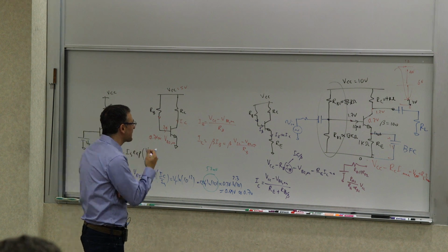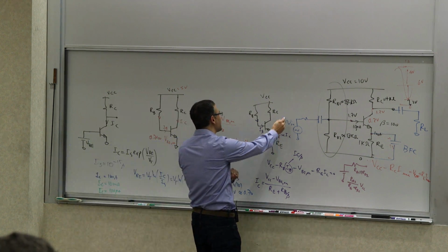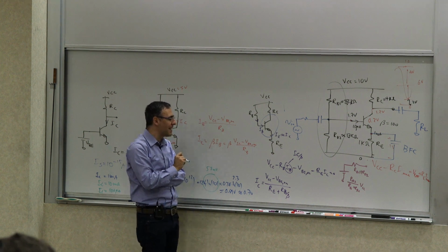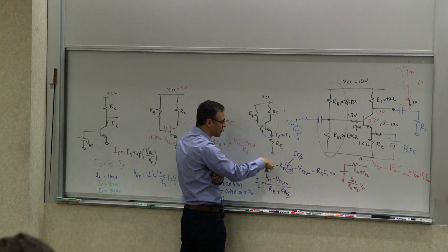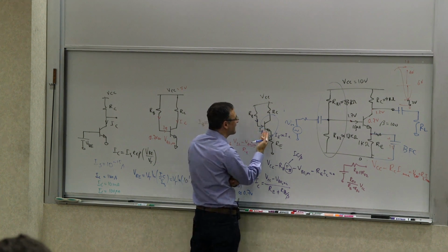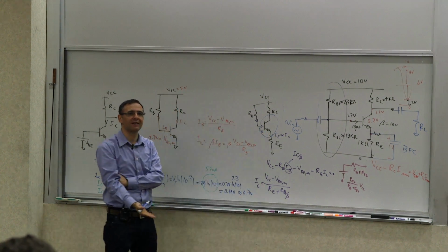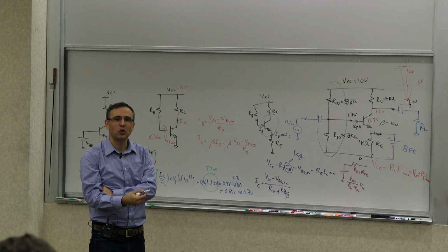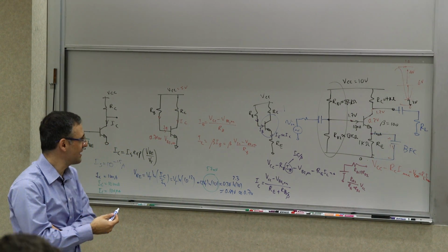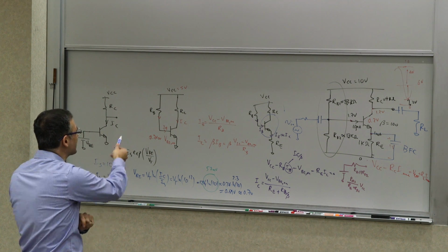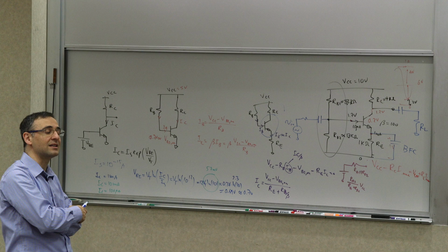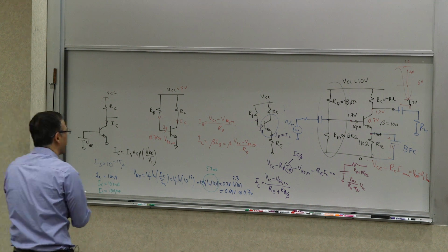Now, the interesting thing about this is that by biasing it this way, if you choose the values such that you have the proper relationship, you have effectively made it less dependent on the specifics of the transistor. You don't see the exponential there anymore, right? In the biasing, you don't even see the exponential much in the gain characteristic if you don't have the bypass capacitor.